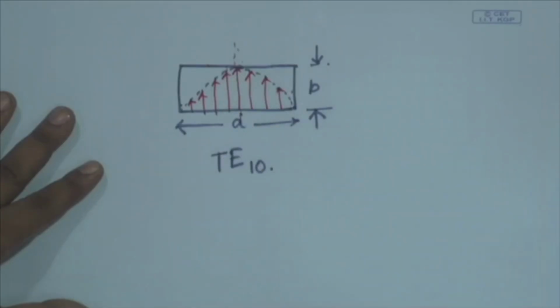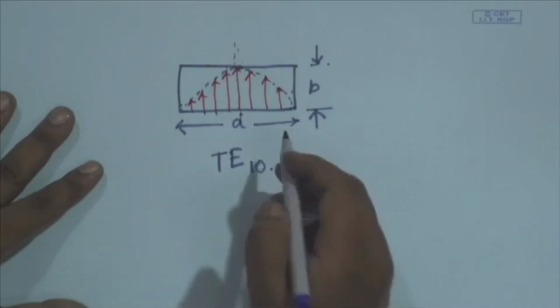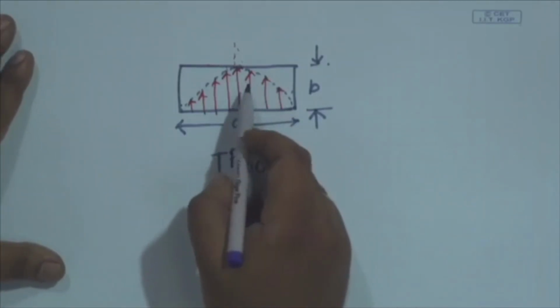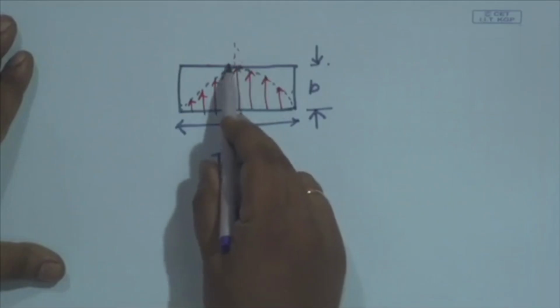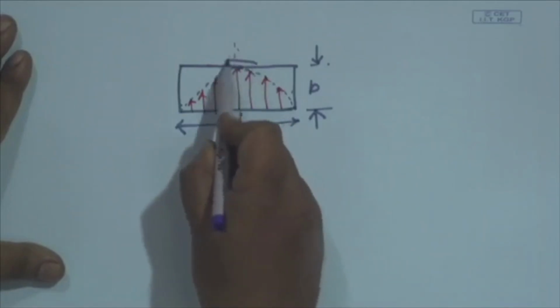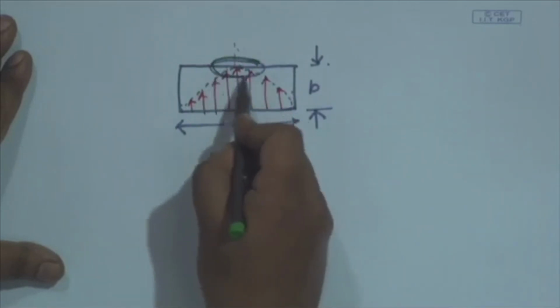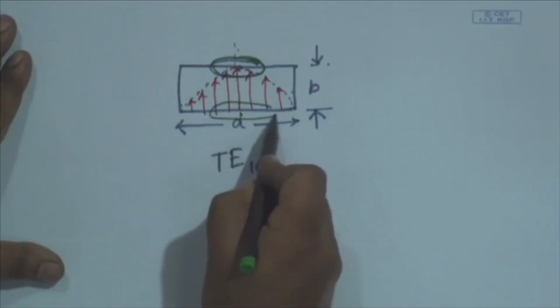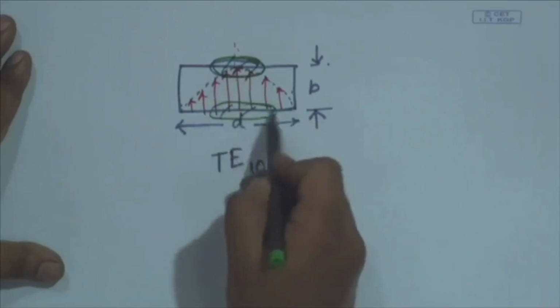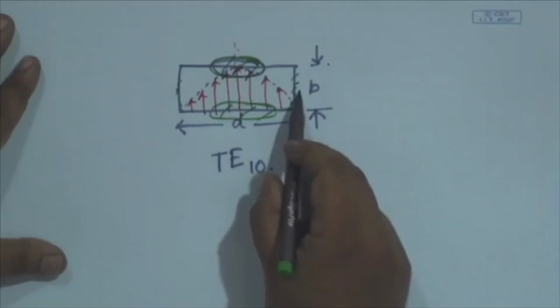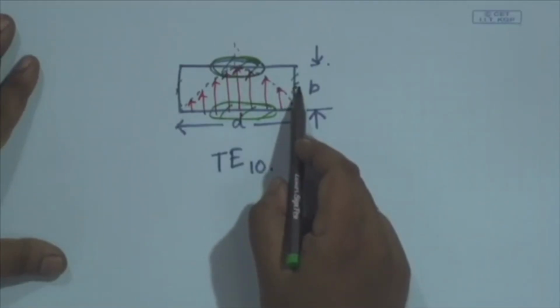So, if we want to inspect from which place the conductor loss is coming, it will be mainly from this middle part, where JC and JD have highest value, and on side walls the contribution of loss is approximately 0.